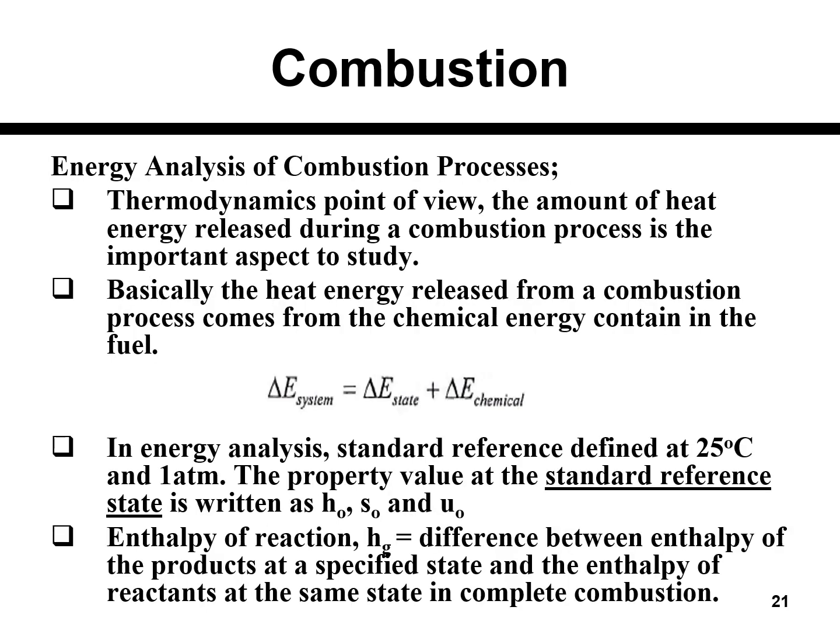Okay, so next we're going to look at the energy analysis of the combustion. Previously it was just the combustion analysis. In the energy analysis of the combustion process, from the thermodynamics point of view, the amount of heat energy released during a combustion process is the important aspect to study. So we're going to use the first law of thermodynamics to calculate the energy released from the combustion process, which comes from the chemical energy contained, which is the change of the energy state plus the change of the chemical energy.